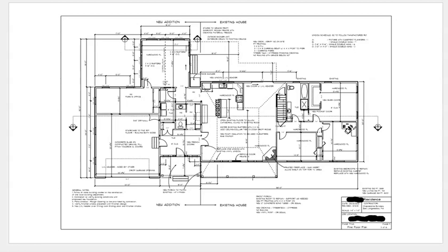You can see this is actually representing my cathedral, a new cathedral that was built in here. You can see the object lines everywhere. You can see cross sections. This is a horizontal cut in our structure, right? So we're looking at this in 2-dimensional. You can see all the doors and the windows, even the cabinetry and appliances. Hidden lines, this is representing a proposed deck that's going out back. There's a front porch over here with a beam. You're going to see some hidden lines there as well too, and all sorts of general notes.